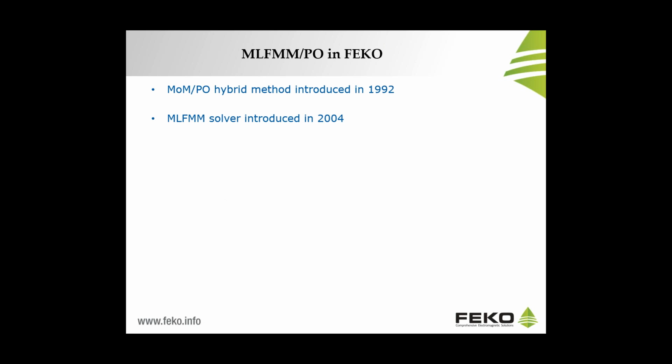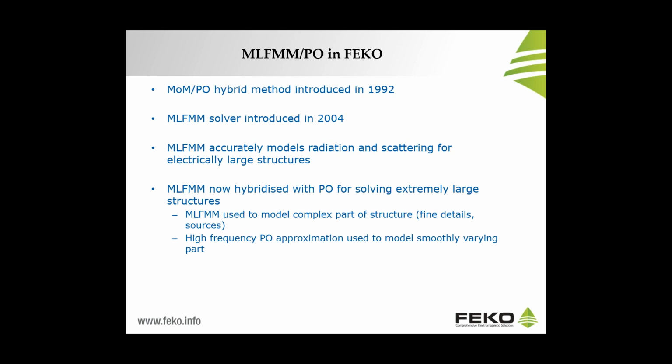In 2004, MLFMM, a full-wave method especially suitable for the analysis of radiation and scattering problems involving electrically large structures. And now with FEKO Suite 7.0, we are introducing the hybridization of MLFMM with PO to solve extremely large structures, where MLFMM is used to model the complex part of the structure, the fine details and the sources, and the high-frequency physical optics approximation is used to model the smoothly varying parts.